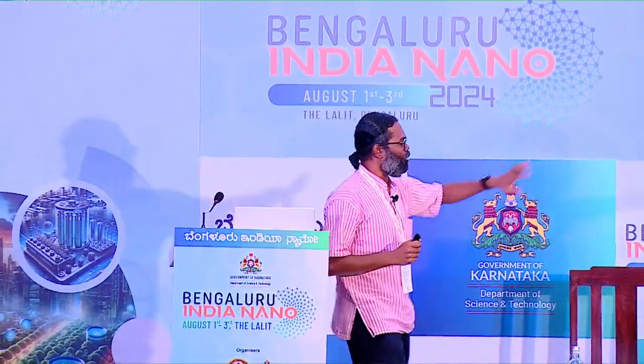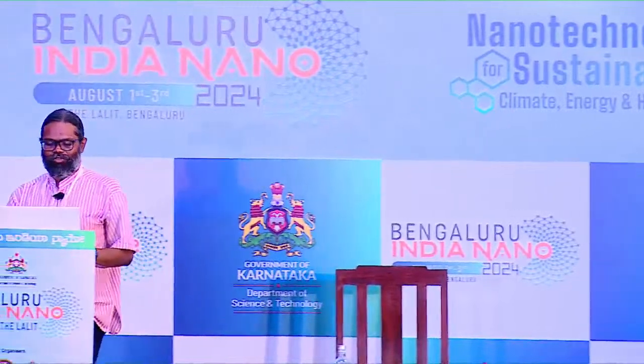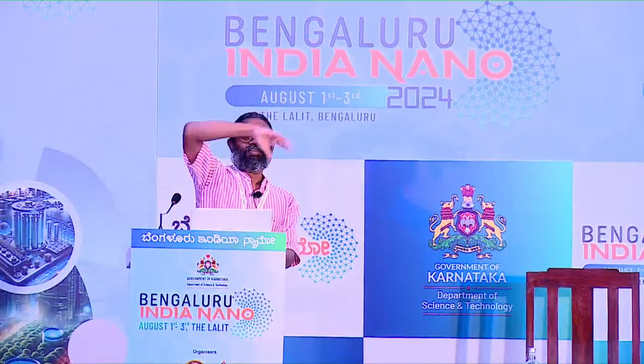At the end, if you keep on building up all your metal lines, you will end up with such a stack. On the right side, what you see is the top-down image of an i7 processor, which is wire bonded. You see all these pads, and that is where we are connecting those pads to the external world, okay? So that will complete the whole fabrication of a chip, right? Starting from the transistor to the complete bond pads, and you have your final product, okay? So I'll stop here, and I can take questions or doubts that you may have.